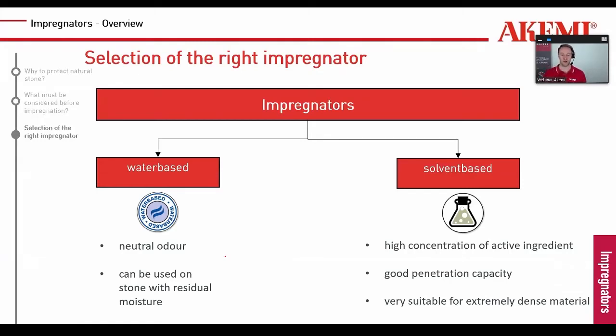Or when it comes to outdoor application where you're not sure, is this stone dry? Am I sure if this terrace material is dry already? Then I can take a water-based sealer or impregnator because they can stand a little bit of moisture. Of course, the stone should not be dripping wet. The surface should be dry, but some remaining moisture inside the stone is not an issue for the water-based product.